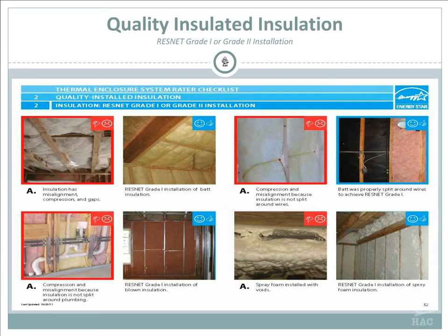And then the next one shows a good example of how that should look. They're not showing the same picture insulated before and after, but it shows a good picture of how it should look. Again, you're starting to see a lot of foams come on the market. You get these wet foams that go on wet and sprayed. You've got to be real careful, and make sure that whoever's doing that knows what they're doing, because that foam does expand and you could end up with a mess if it's not done right. The one on the left, you can see how it's done: a lot of voids, a lot of overspray, and so on. The one on the right, on the top there, really doesn't matter because that's going to be sheetrocked, so you won't be seeing that. That's a good job.